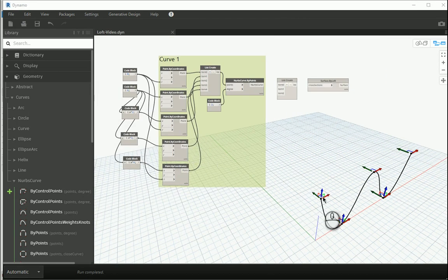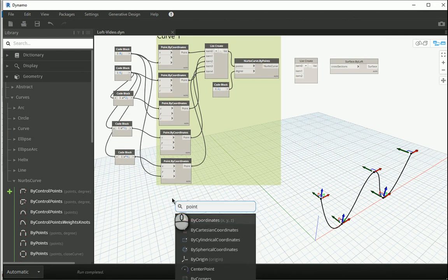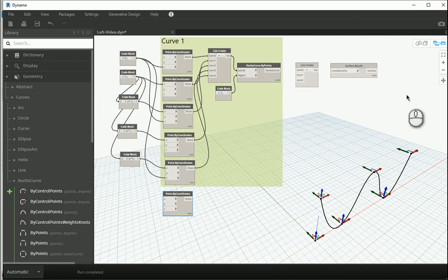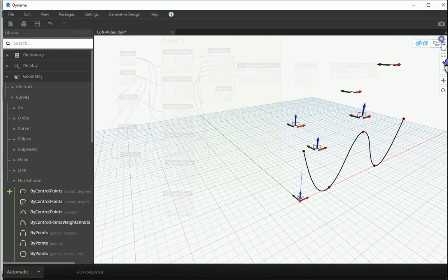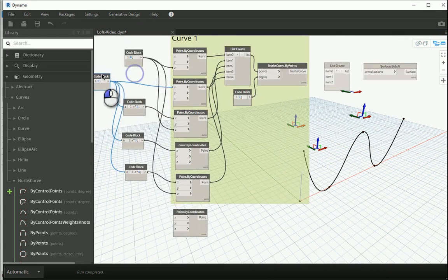So next I want to create the second cross section here. So let's say maybe we have another point, and if from here to here it was 6 meters, I want to move this point in the green axis, the Y direction, by 6 meters. So I want to assign that 6 that we had to the Y. So now the point is over there.